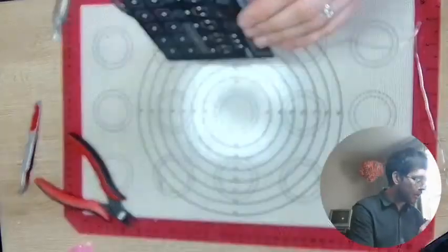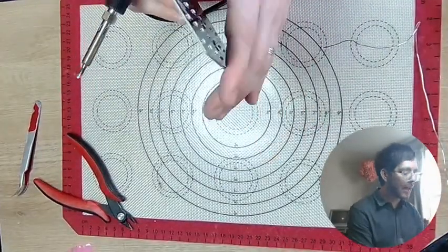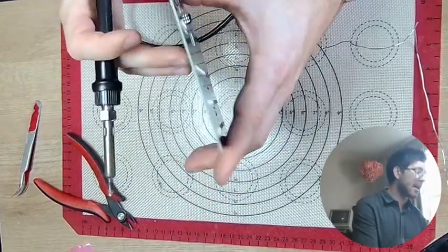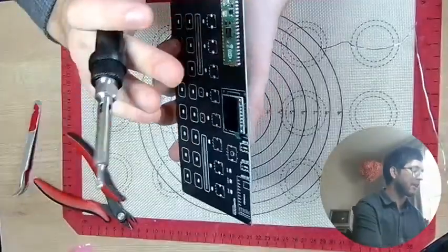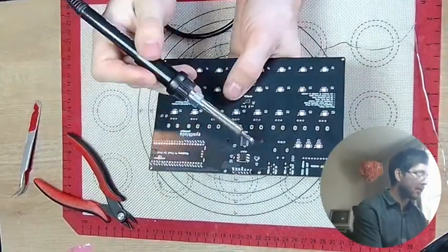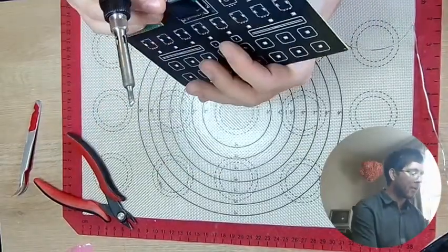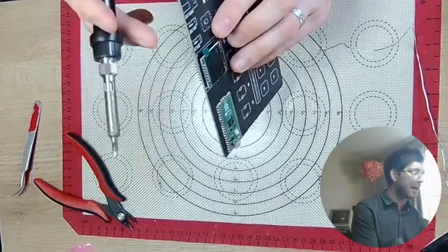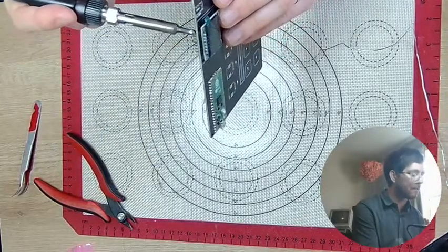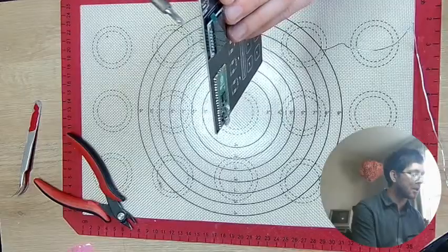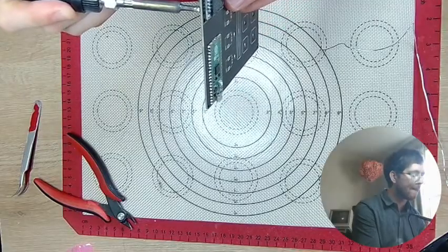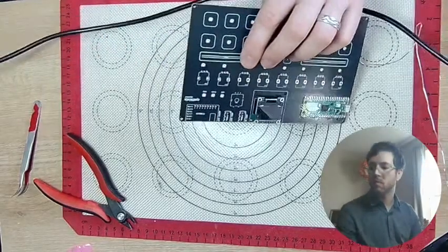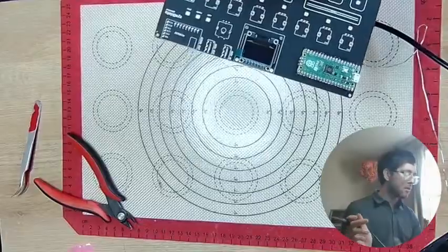Okay, so what y'all may have noticed, there's a little bit of a gap there. I don't know if you can see that. I wanted to straighten it out because whenever you solder up first, it might be bent, a little crooked. So I soldered one leg and then went back, lifted it up a little bit and reflowed the solder on that so I could level it out, which I might want to do again actually. And that helps you get it level. I think that'll work.